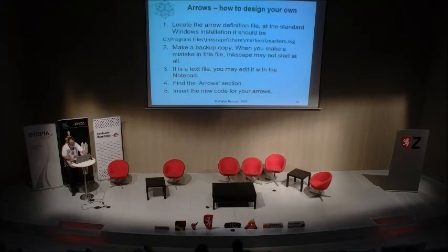We may design our own arrows. First, we must locate the definition file at the standard Windows installation. It is at the location in the share directory, the markers.svg file. First, make a backup copy.